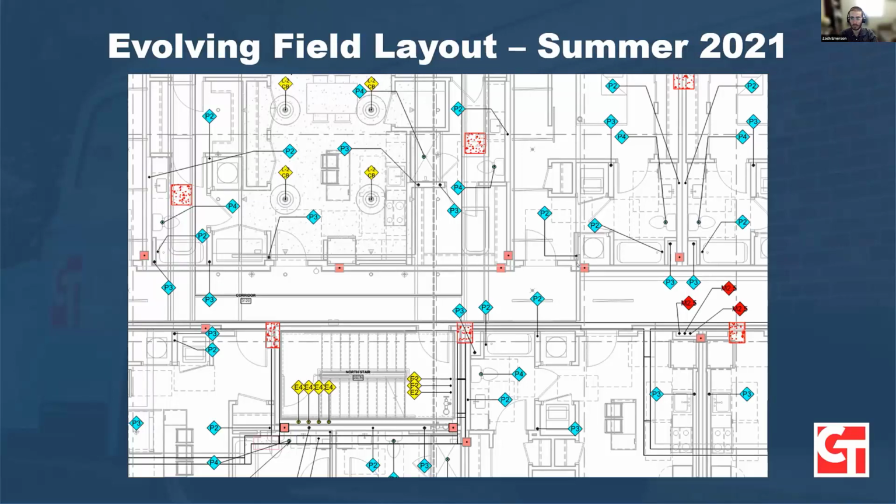Typically for coordination, we work closely with our mechanical, electrical, plumbing contractors to get their sleeve locations identified, whether it's a typical unit plan for repeated unit layouts or more specific needs for risers up through the building, things like that. It's a very involved process. We usually would sit down with them and go through one by one and designate dimensions for each fixture type or each unit type to really get those sleeves located as accurately as possible.